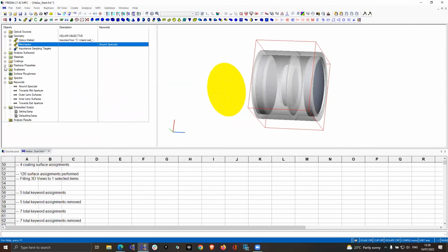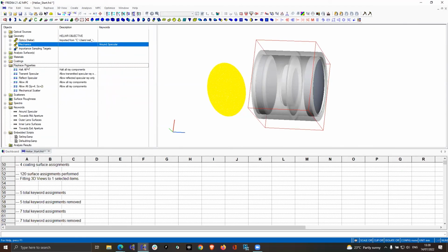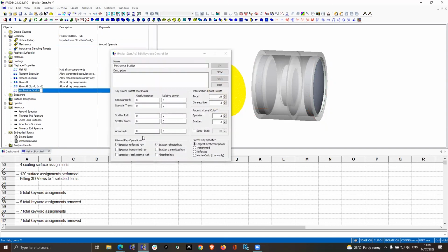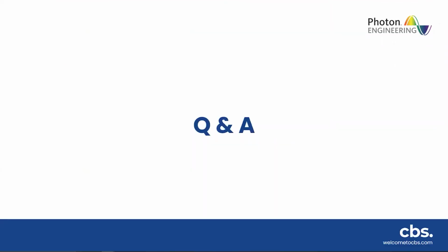So once we've allowed a specular reflected ray, we have to decide what power that ray has, and it's the coatings that tell us how much power that ray has. In this very simple demo, we said we had a 100% reflective coating, which essentially means that the specular ray has all the power that it should have after the energy for scattering has been taken out, but there's no further absorption. Hopefully that answers that question.